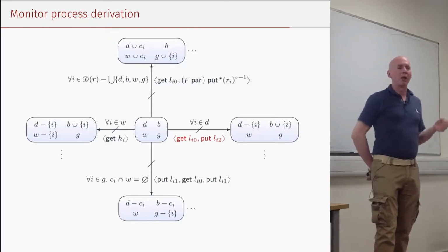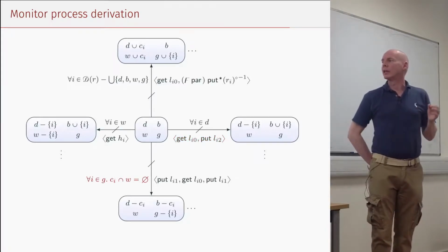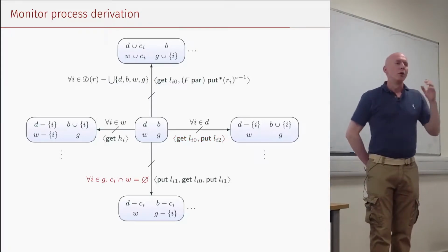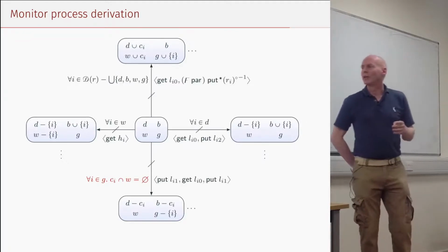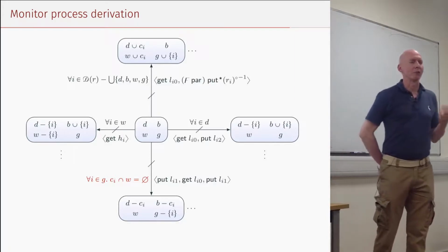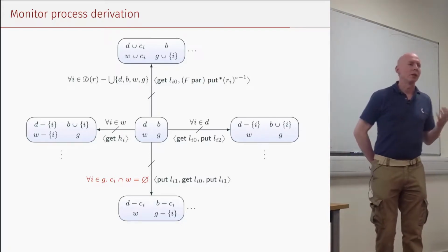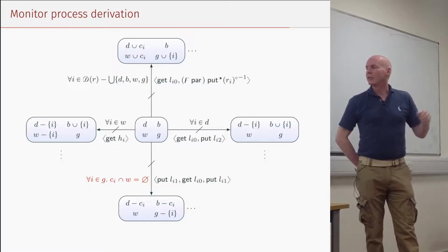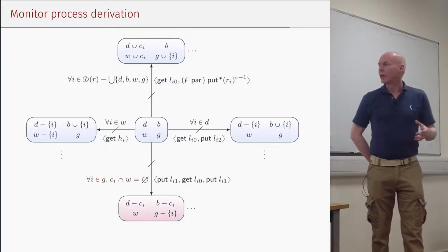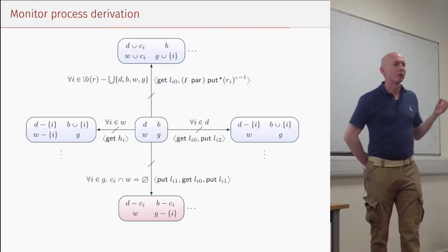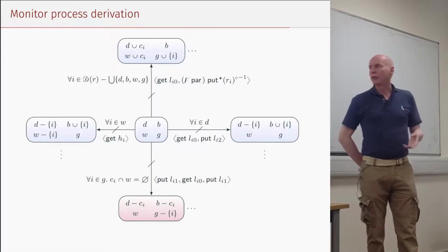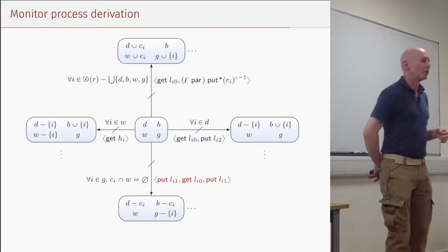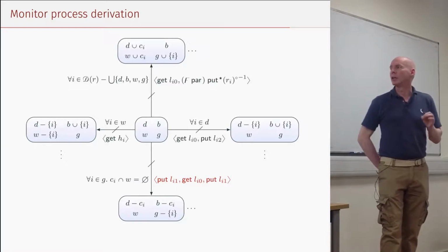One more possibility, a transition I belonging to the set G of grantable transitions whose competitors, significantly, do not belong to the set W of transitions from which revocation acknowledgements are expected, meaning that it would be safe to grant a lock to that transition I. In that case, there must be an adjacent vertex where I is no longer grantable, its competitors are no longer blockable nor deniable, and to have reached that point, the monitor must have completed this successful 4-phase lock negotiation handshake with the ith transition. So that was a bit of a mouthful.